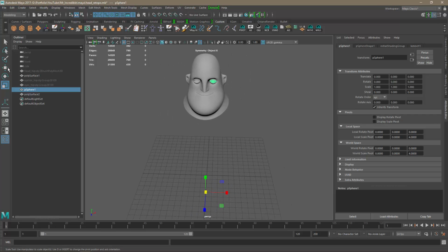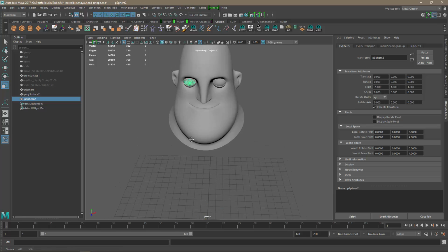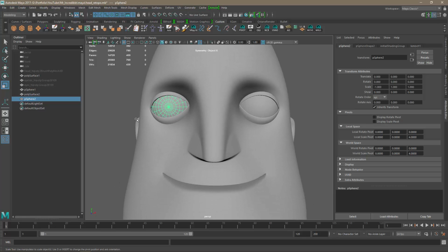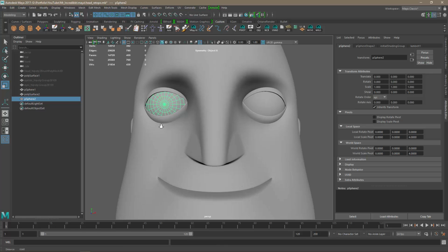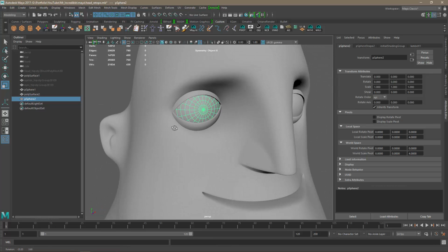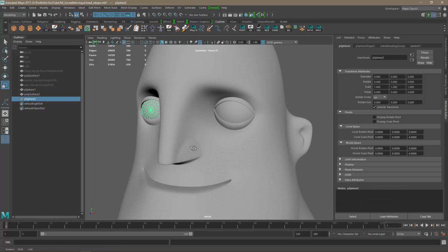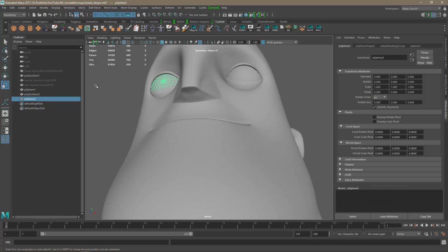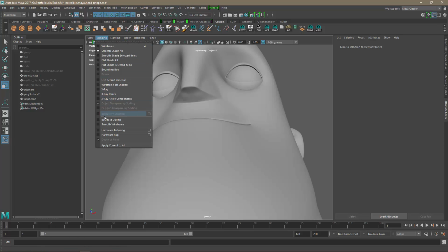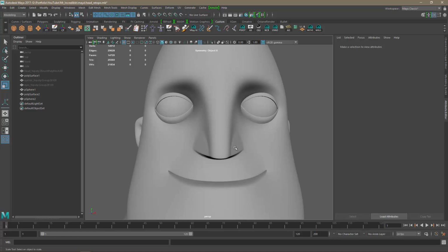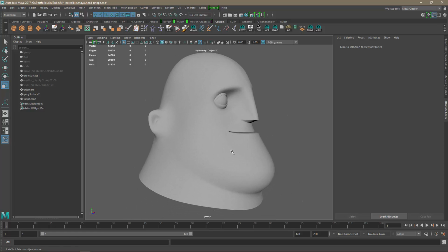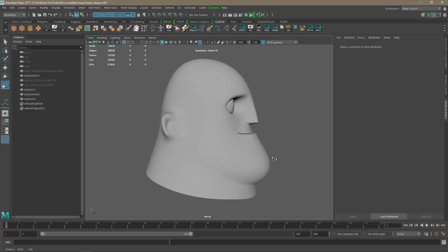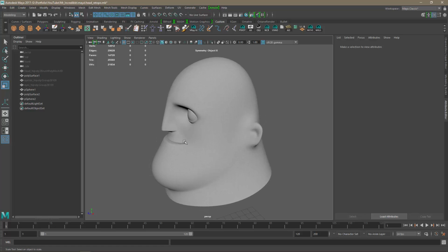And now I can just duplicate this guy, and I'm gonna scale it -1, so it goes back exactly mirrored to the other side. Freeze transformation, and this should do. I'm not sure if I have to flip the normals. Let me see. Face scaling, no, it looks fine from here. Okay, so I think this should work.